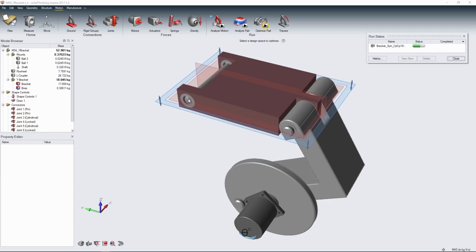It is nice that I can run the simulation in real time during a live webinar. It really does take just a minute or two, especially for an initial analysis. If I wanted something very precise or a very smooth result, I would bump that mesh control or the minimum thickness down a little bit, and then the study times can go up to maybe 10 minutes or so, but for the most part, we keep them at under 10 to 15 minutes.